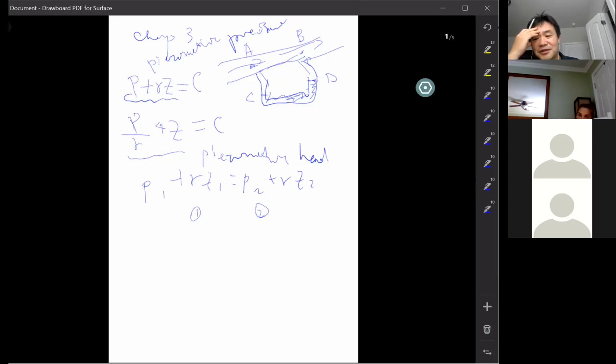A different way to solve the problem. But you can always use piezometric pressure, hydrostatic principles, A and C, so you can convert A and B into C and D. Between C and D, the pressure difference is obviously from the manometer fluid. The deflection of the water level between C and D indicates the pressure difference between C and D.